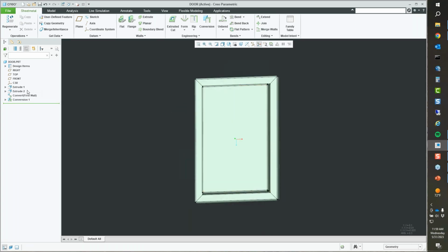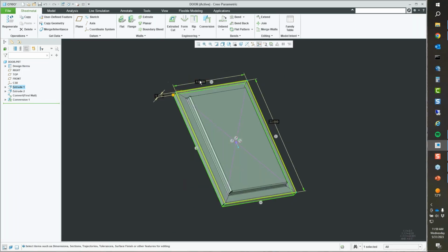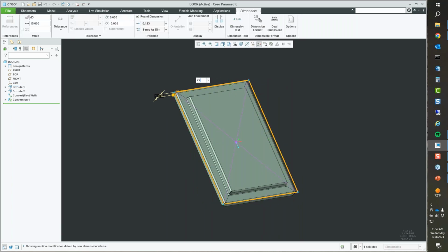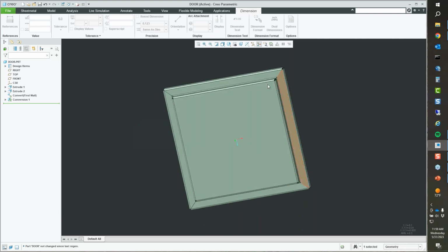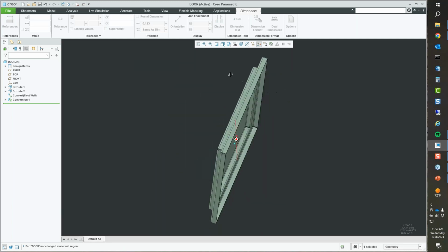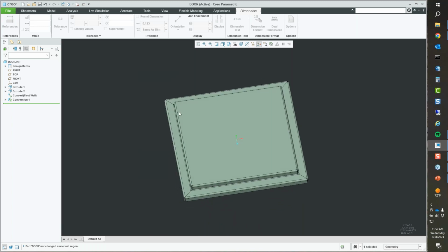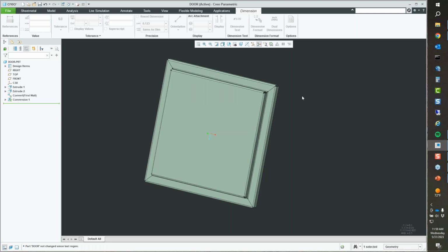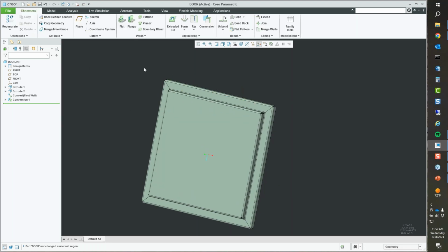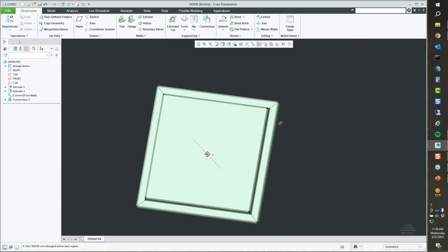And then if I modified the original shape, which is the reason why I did this in the first place, I like it because it will automatically update everything. And I can have one door shape as a template and then use it over and over and over and over, right? That's the goal, I got some shape that I'm doing 1,000 times. I want a very specific layout of the flat. This is the reason why I do a solid part and convert it to sheet metal and then use the conversion tool to get what I want.